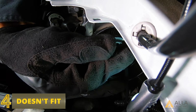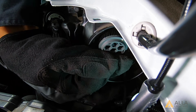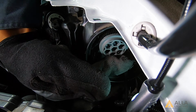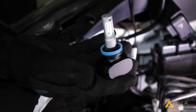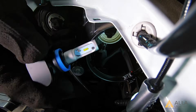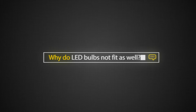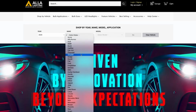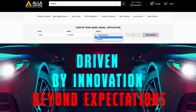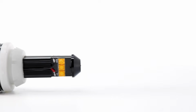4. Does not fit. What are the cases that LED headlight bulbs do not fit? The most reported problem by consumers is that the LED headlight bulbs are too big and they cannot put the dust cover back on. The second is the LED headlight bulb's diameter is too large and conflicts with the housing. Why do LED headlight bulbs not fit as well as stock incandescent bulbs? The first cause is the wrong bulb size. Be sure to use a bulb size tool to find the correct bulb before you make any purchases to avoid a simple but time-consuming mistake.